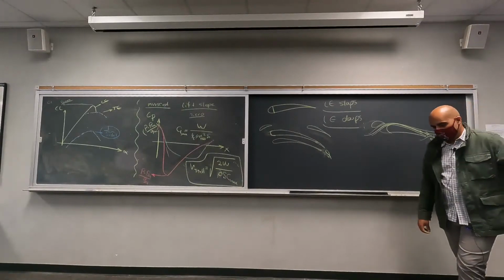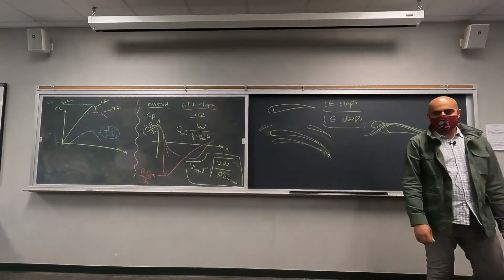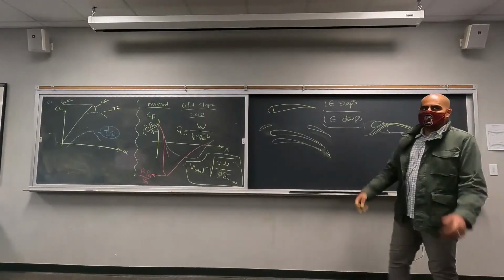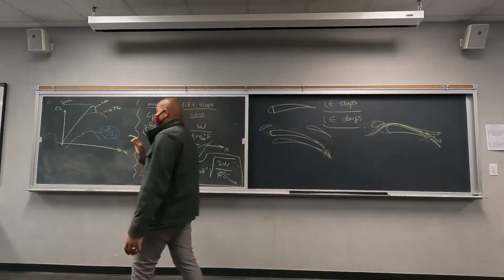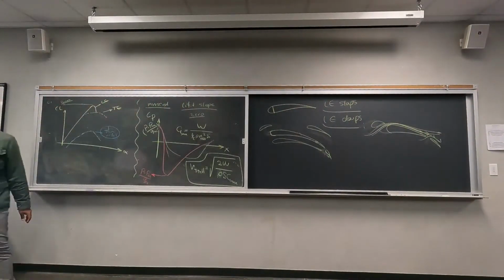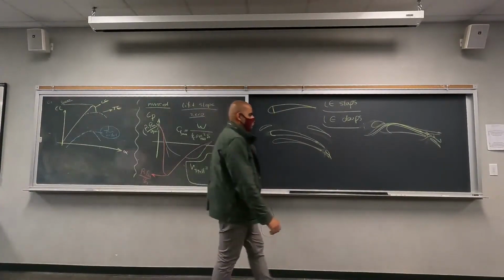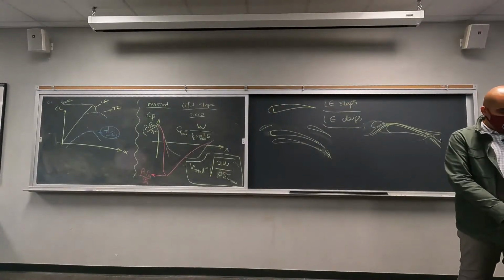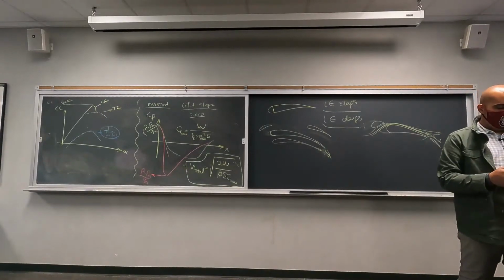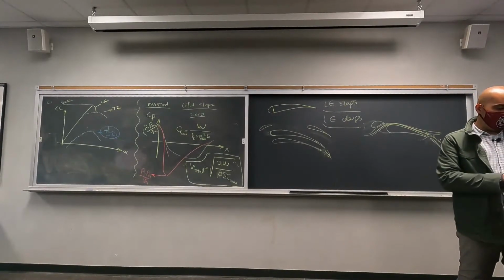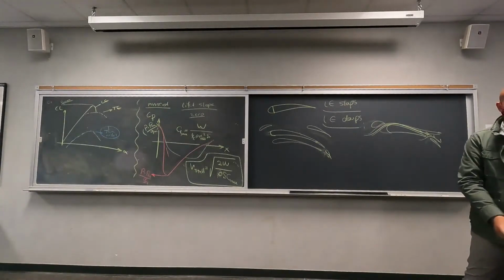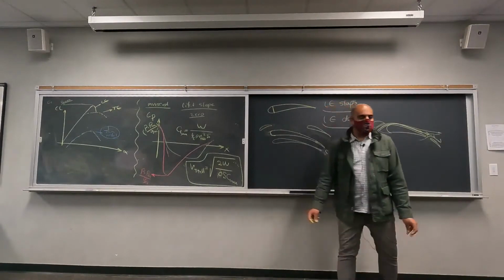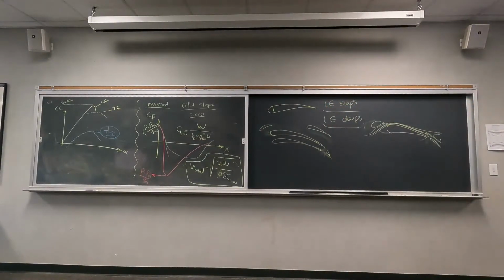Thanks for all of you chiming in. Okay, so we understand the high lift devices. We understand the two different mechanisms by which the high lift devices act: to increase the lift coefficient, or to delay the separation and increase the angle of attack at which your airfoil, your wing, can operate. There are many different types of these flaps and slats, and I have some more things on the notes that I have uploaded on Blackboard.